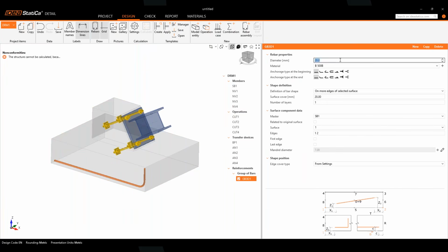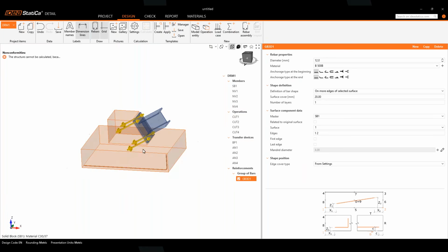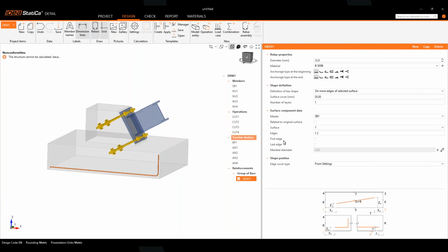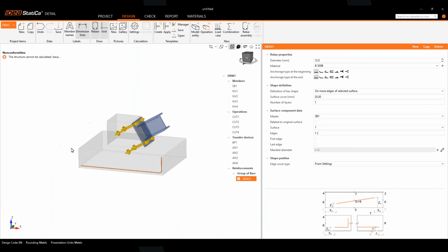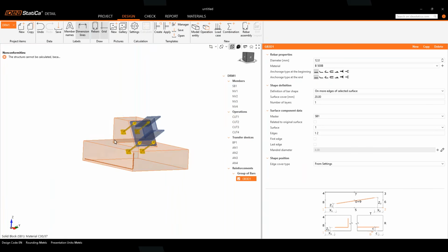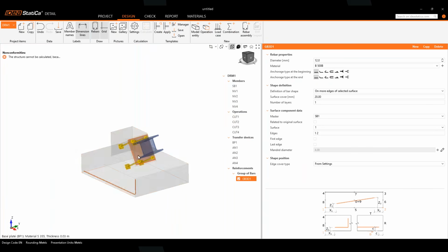And from there, I just want to make use of 12 mm for the slab, because this is anchored to the base slab. I'm also going to make use of continuous member, because in this case, this is a whole slab and we only model a partial of it.